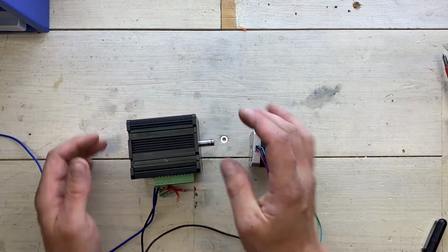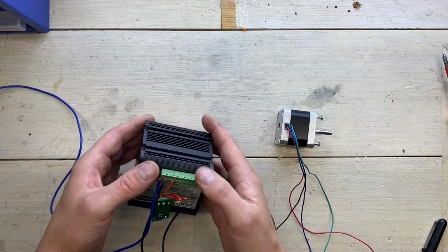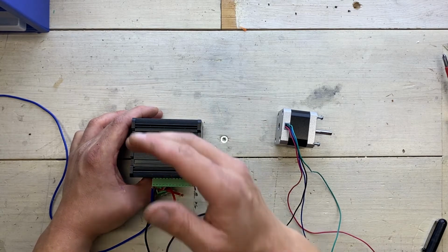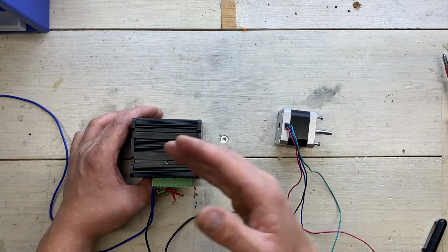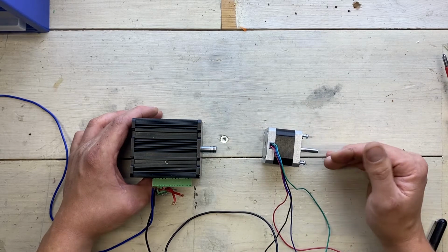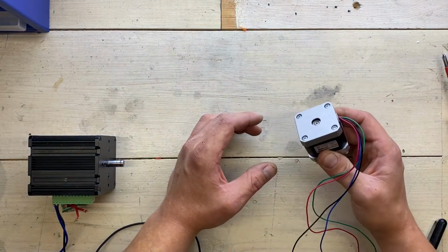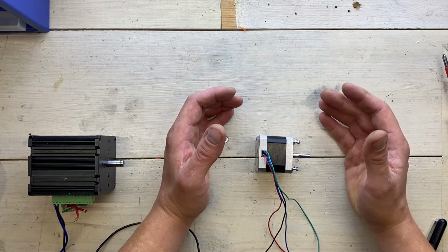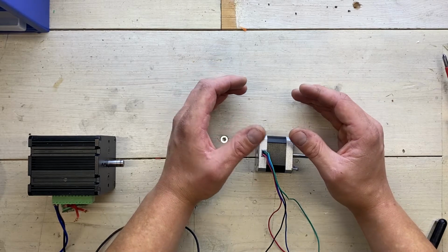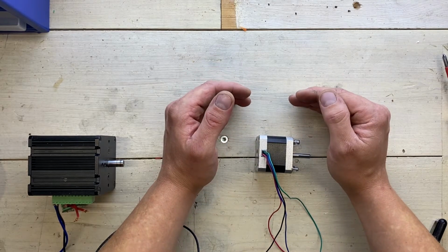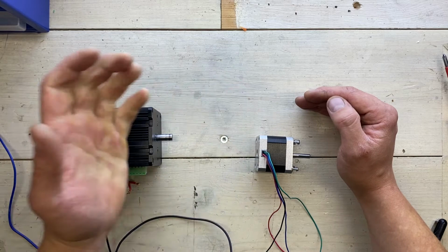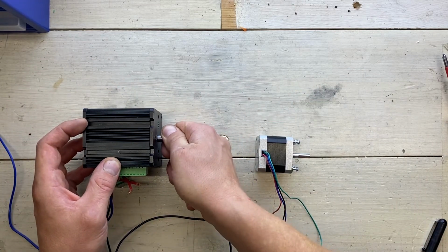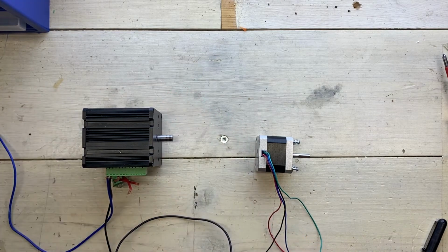Now an AC or DC servo, however, you can simply increase the current and increase the voltage until it's at the correct position. But you can't do that with a stepper motor because then it starts losing steps. What you can do with a hybrid servo, however, and which is implemented in all the better drivers out there, is you count the steps and then you let the motor run for a little bit longer to catch up the lost steps. And this is also what servo drivers do. It keeps the motor running until it's at the correct position that you told it to move to.